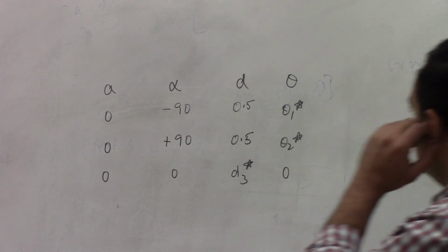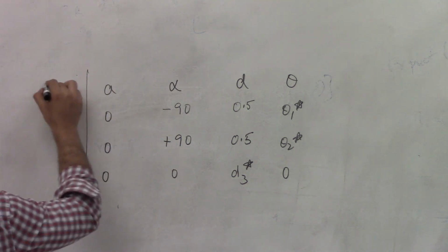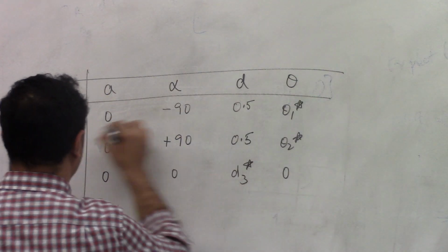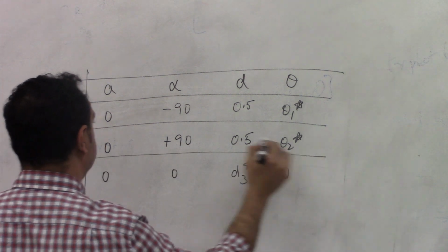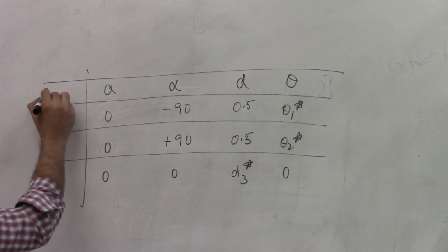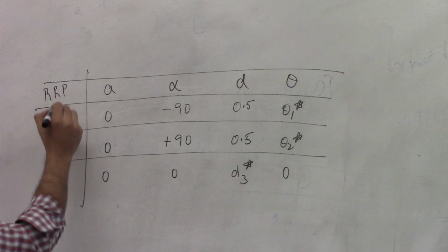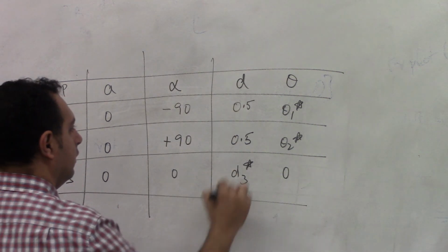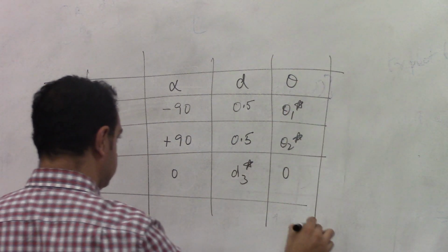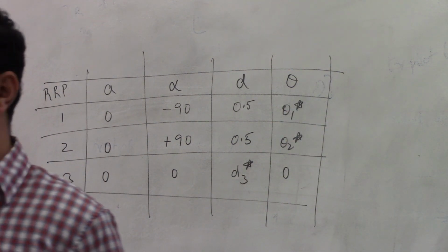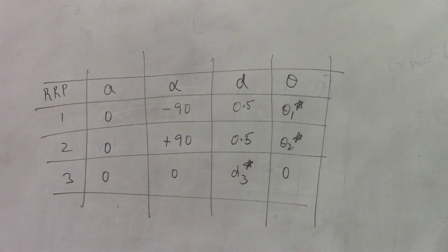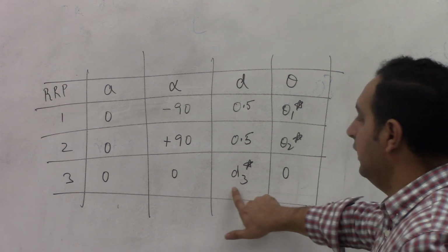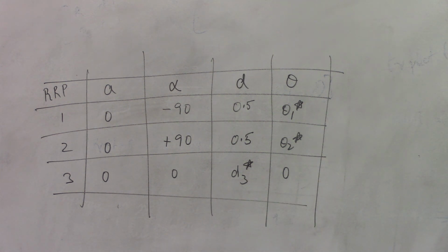Okay, so this is an RRT manipulator. Let's try and set up the manipulator for this. Let's try to write the DH table, and I'll show you what happens when you do a DH table for this, especially when it comes to the last link. Okay, the first two are easy, let's do that.